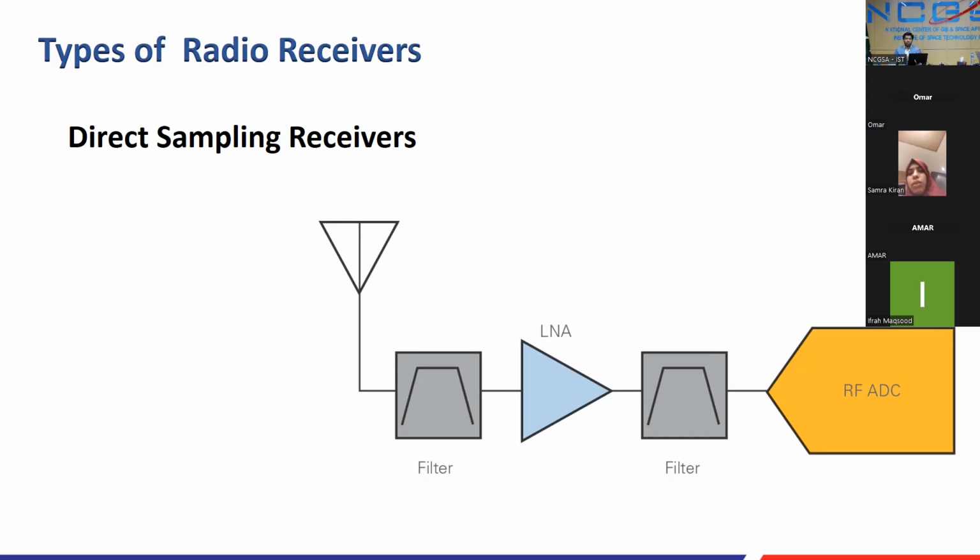In this particular configuration, as we move towards the next session, I will share. It is a high side injection mechanism, as I have explained earlier, where your LO is on a higher frequency than your RF frequencies. In that case, the actual mixing products can be rejected if you have precisely placed the frequency responses, the frequency planning. When we move towards the software part, I will explain how we do frequency planning before implementing a receiver. That is actually a crucial part.